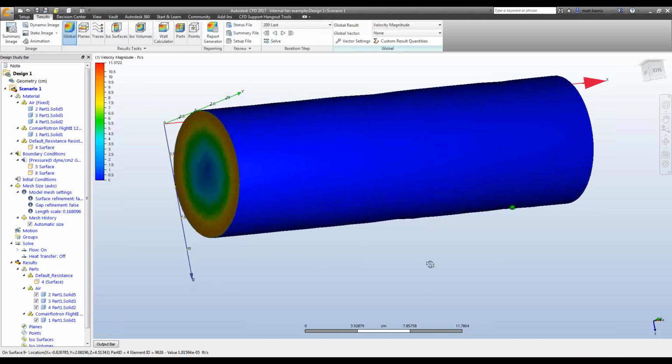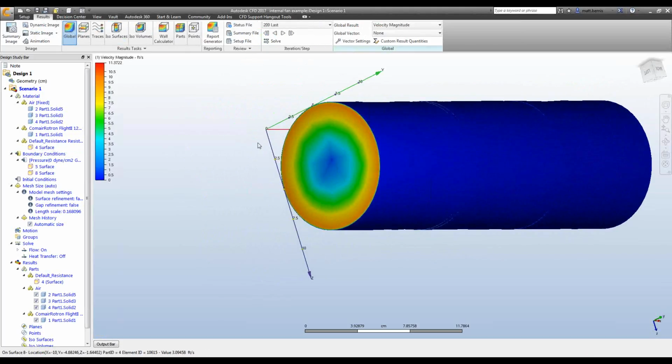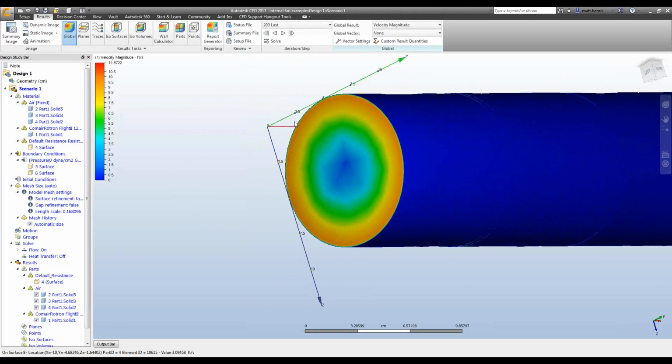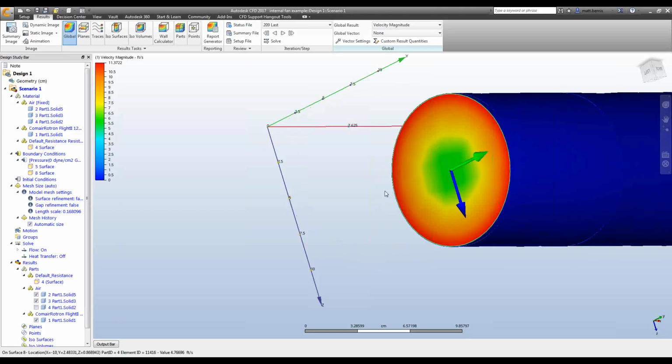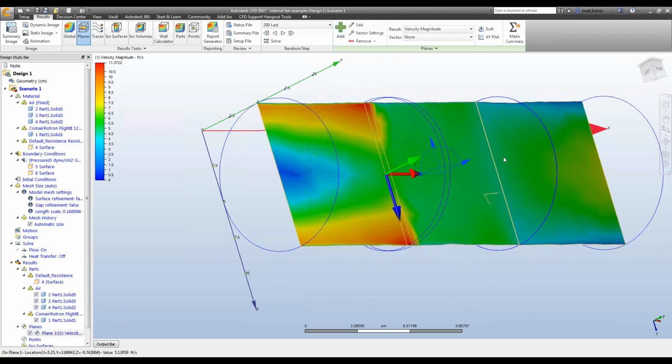So these are my results. Now you'll see this is on the downflow side, basically the outlet. You'll see there's a higher velocity around the perimeter, and that's because we have that rotational speed specified. Instead of directing a flow that's just normal to the outlet, basically this face, it's actually going to have a higher velocity on the outside, just like a fan blade would, which is great to see. And I'll show you pressure in a Y.